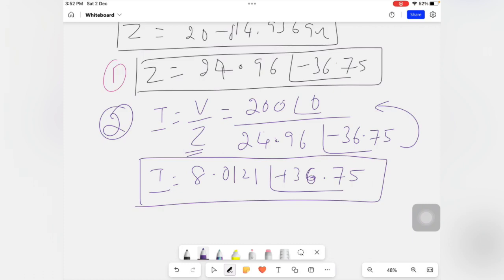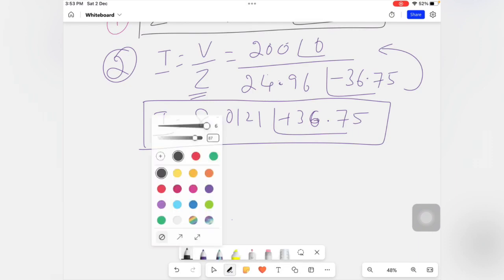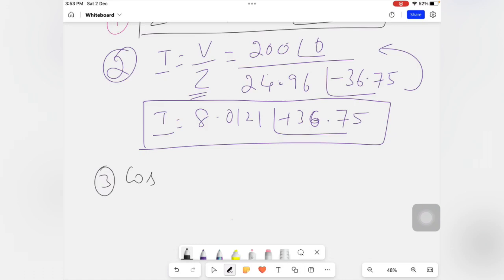Now as I said already, if the XC value is greater than the XL value, then it is a capacitive circuit. Now what is power factor? There are three definitions: with respect to power, with respect to impedance and resistance, and with respect to the angle between the current and voltage. I will use another formula for cos phi, the third one. Cos phi is equal to R by Z, because we know R and we already calculated the Z value.